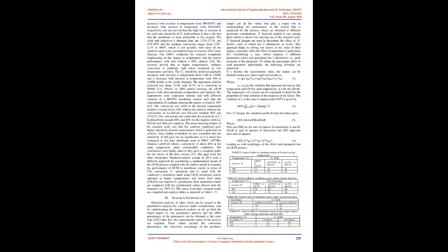stating C2 yield increases with increase in the temperature. As far as the C2 selectivity is concerned, it increases with increase in temperature from 800-850 °C and decreases with increase in temperature from 850-950 °C respectively, and he also proved that the high rate of increase in the yield and selectivity of C2 hydrocarbons is due to the fact that the membrane is more permeable to the oxygen.